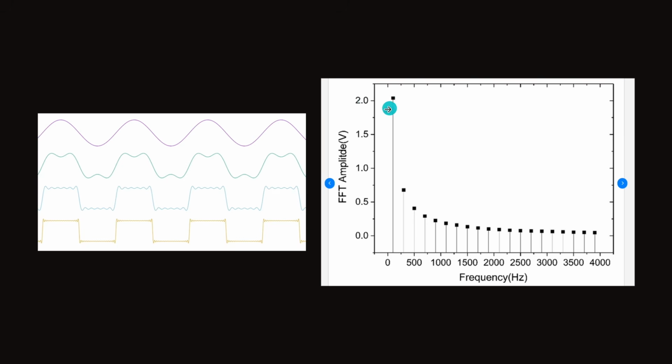The more you clip, the more harmonics it has. And those harmonics are at low level, but recalculating, if you have clipping at 300 watts, then each of these harmonics is about 4 watts. Yeah, and those are summing up.